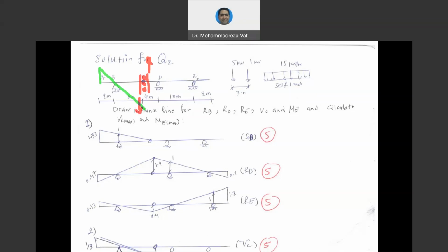However, for the right side to move, we need to see whether this rod can move or not. Again, you can see we have two support reactions at the same time. If we push this one down, the support reaction at point E doesn't allow this rod to rotate. Therefore, our influence line is going to look like this shape. And since the imposed displacement is unit, we're going to have -1 here, and the other side can be easily calculated through mathematics. So this is going to be the influence line for VC.